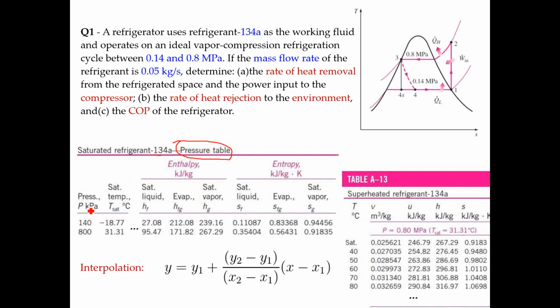And that gives you the pressure at which you will have the enthalpy H or entropy S value. And also, this is saturated. So when you are doing practice, be really careful about the states. When do we need the saturated refrigerant? And another one, when do we need superheated refrigerant?